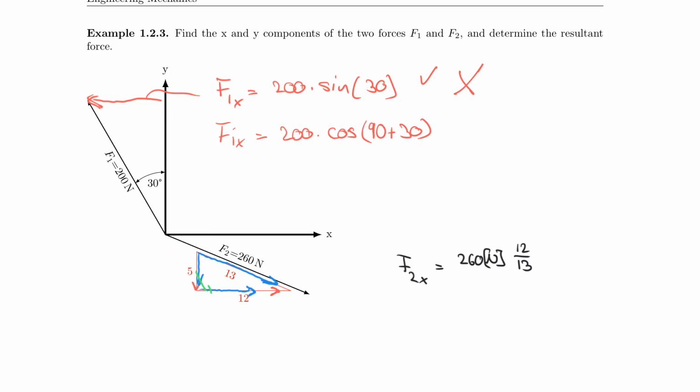So what I'm trying to really tell you here, and what I want you to form as a habit, is to always move an angle from the positive x to the positive y, and so therefore it's counterclockwise, right? So always measure your angles counterclockwise from the positive x to the positive y. That is very important. When you solve problems like this, you might get away with what's given here on the top, but so this will work, of course, and if you do it rigorously and always correct, it's fine.